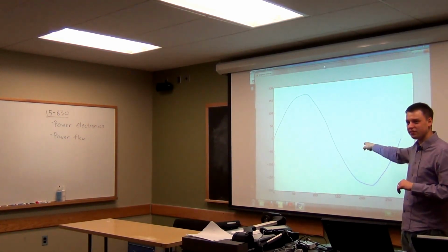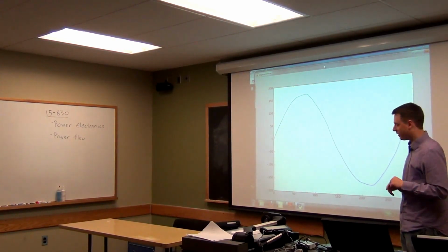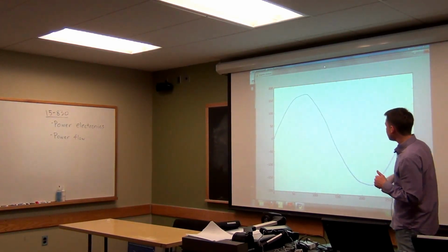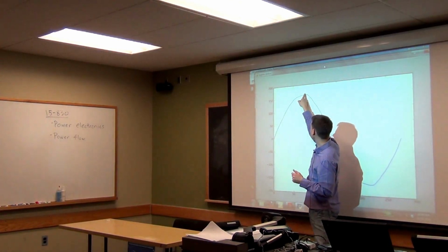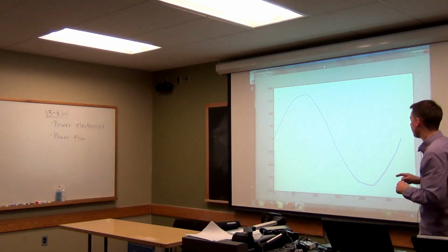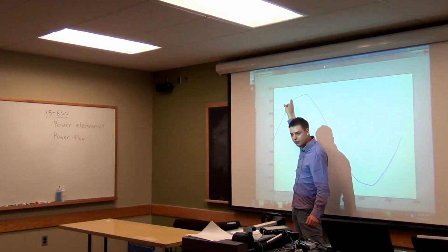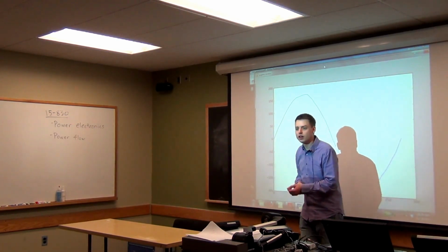And we can see this actual voltage signal from the outlet here. And it's not, I guess, perfect. There's some things where this is not quite a perfect sine wave, but it's pretty good, right? This is sort of a pretty good sine wave here. As we expected, the maximum is at about 170 something.